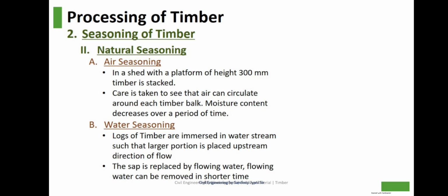Natural seasoning. Air seasoning. In a shed with a platform of height 300 mm, timber is stacked. Care is taken to see that air can circulate around each timber. Moisture content decreases over a period of time.